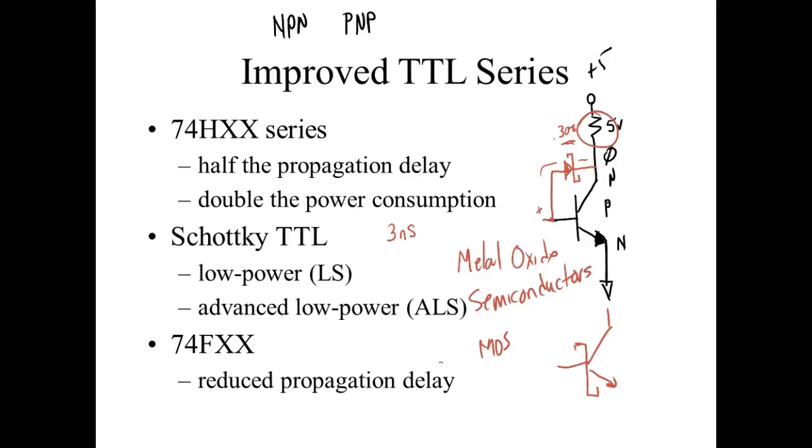So right off the bat, I could come over here and literally have an inverter, and this is simple, and put what we call a PMOS up here, put an arrow in, and then down below it I would put an NMOS. So this is a PMOS pointing out, an NMOS coming in, connect these outputs together, and that was an inverter. 2 transistors to get the same thing that took 5 transistors in a 7400 gate.